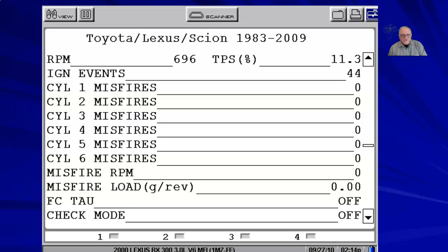When you take the vehicle out, watch this misfire, and you'll oftentimes see that, hey, it'll go to 1 or maybe 2, and then after a while it goes away as it's going through and counting. To have an occasional misfire happens quite often. When you come and look at this and you see cylinder number 2 has 33,449 misfires, and cylinder number 5 has 368, chances are there's no misfires at all on cylinder number 5.